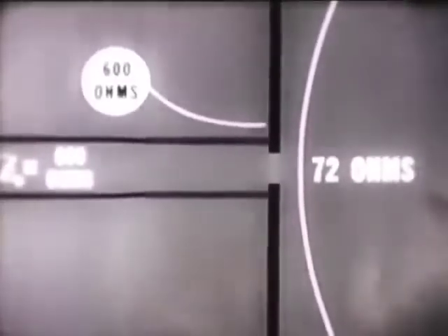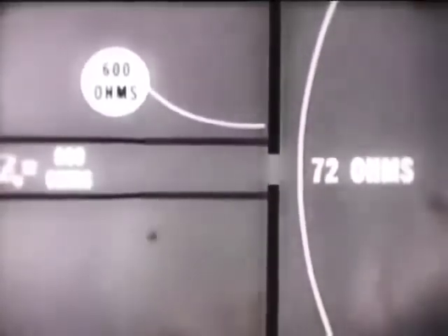As the characteristic impedance of the transmission line is 600 ohms, it remains for us to match this value at the junction with the quarter wavelength line. We can get this matching value by simply shifting the Q bars closer together or further apart, thus changing the impedance until we find a value to match 600 ohms. Once this value is found, impedance matching is completed, and we can look for maximum radiation from our antenna.